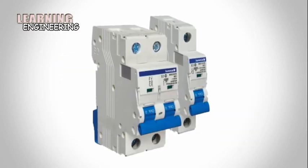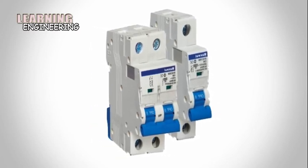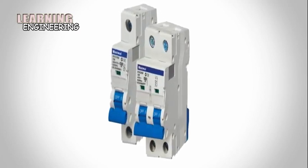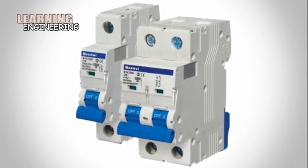Fuses are more likely to be abused because if blown and the user wants to return the equipment to operation and there is not a spare fuse, then he will substitute a fuse of higher value or short out the fuse holder in frustration and defeat the safety of the fuse.